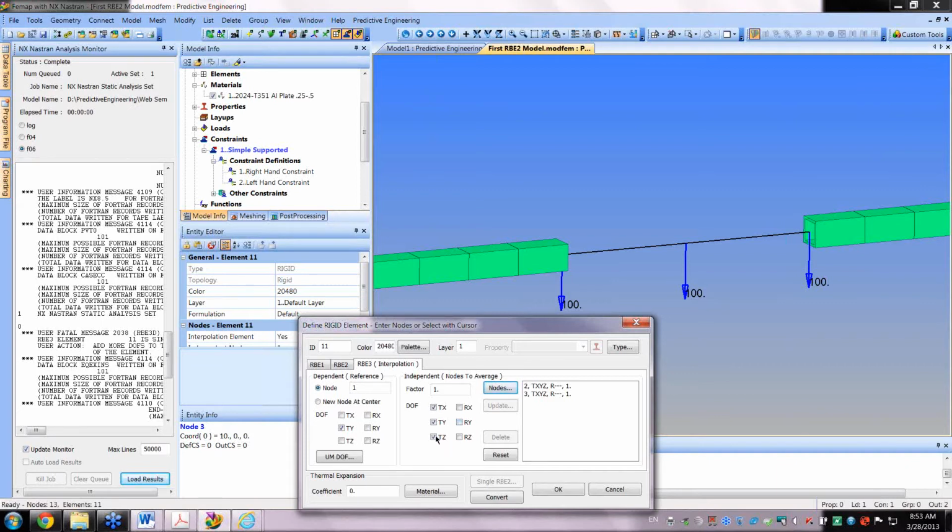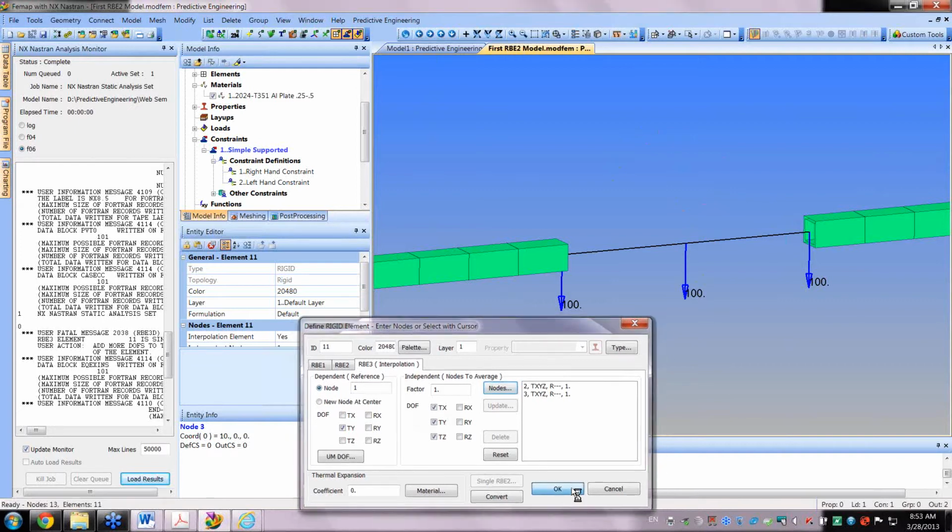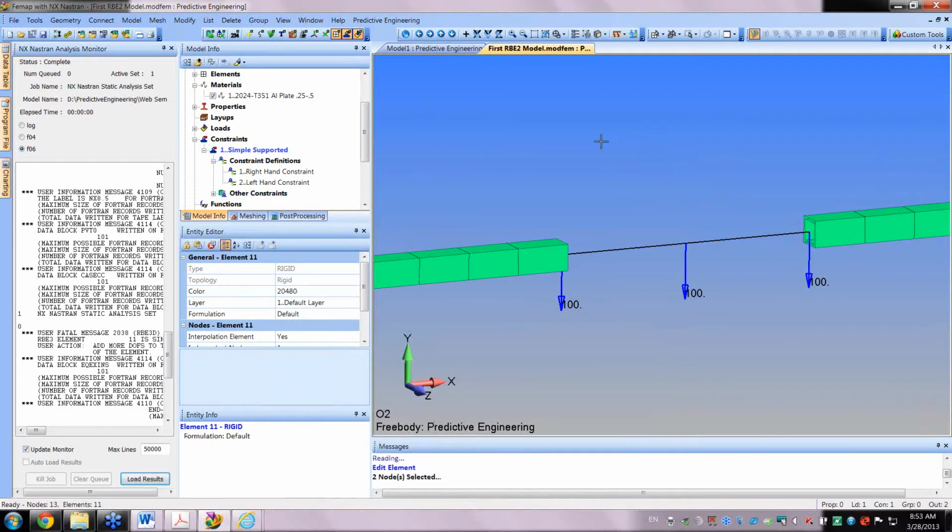But in this action here, if you were to think of this like a rigid body moving in space, you would say, okay, I've covered 3 degrees of freedom here at this point and this point. So it can't move this way. It can't move this way. It can't rotate around this axis. It can't rotate like that. It can't rotate the other two. And we'll just run it like this. Oh, and I forgot to show that.